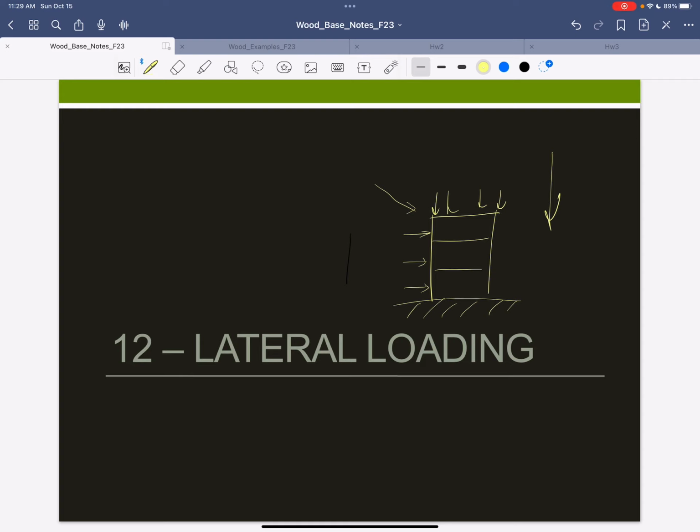If I'm looking at a steel building, for instance, the main basic way, if you're only doing steel, is to have moment connections. So when I go to push this frame over, it can resist that. If you think of a frame from structural analysis that you push over, it does this sort of thing, right? If it's all pins, it would be unstable. But you need at least some of these moment type frames, or you need like a shear wall, right? So this might be a concrete wall.